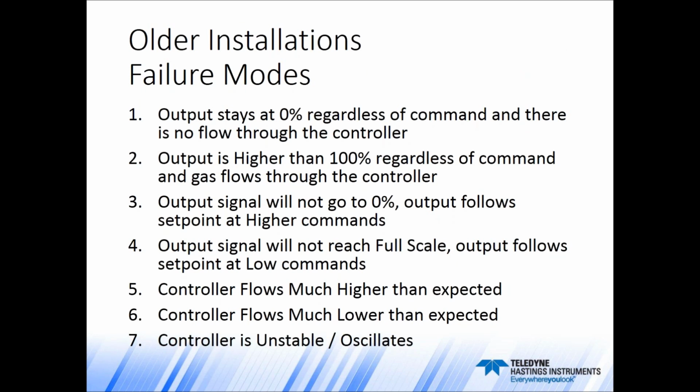These are some of the typical failure modes that we see with a flow controller that has worked in a system and starts to exhibit an issue. The output stays at zero, regardless of command, and there's no flow through the MFC. Output is way higher than 100%, so more than full scale is being exhibited on the output, regardless of command, and we have a lot of flow going through the flow controller.